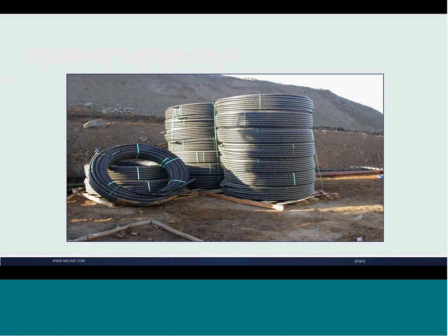Here's a photo of the high-density polyethylene pipe as it is typically provided to a project site. It's typically provided on pallets, and it is typically ordered to the length required. And if it is a drilled or bored loop, it is typically specified and comes pre-configured with the U-bend fused at the end of the pipe. And this is the part that would be inserted into the borehole. We'll get into some more pictures here just shortly.